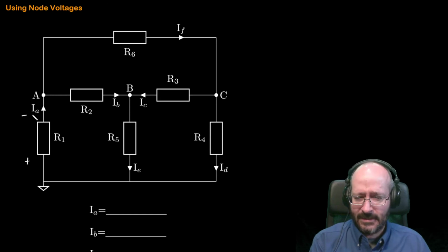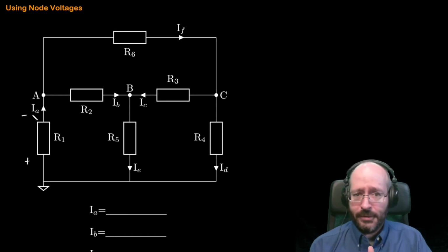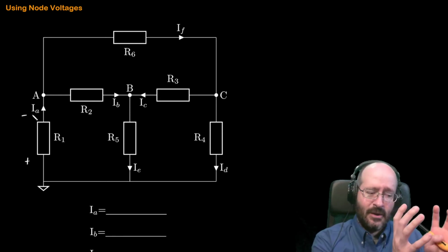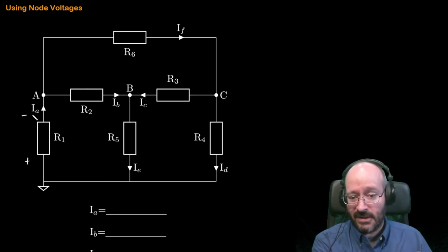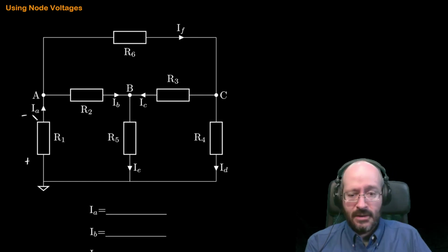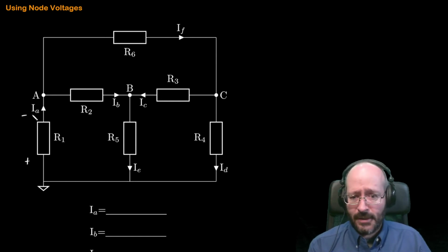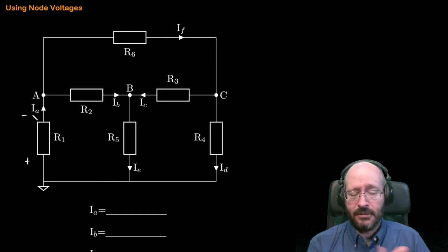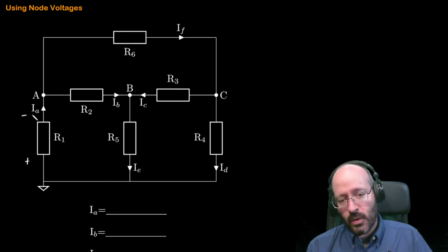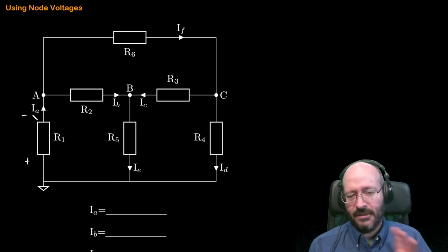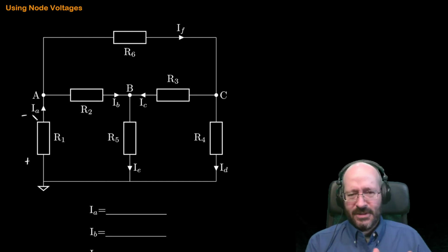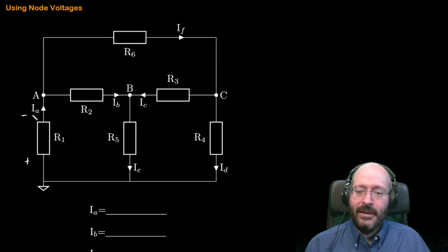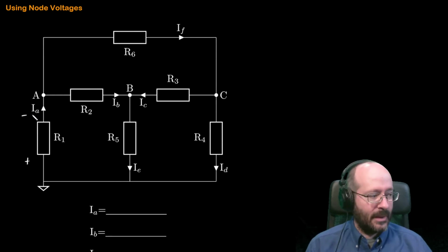flowing through the resistance. And we're going to use that voltage because we've got to relate our non-reference node voltages, even our reference node voltage, honestly, to the current. And we're going to do that with Ohm's law, similar to how we did it with mesh analysis, just backwards. And you're going to find that's the case with nodal analysis versus mesh analysis a lot. There's a lot of overlap, but we're just kind of swapping things around. But the approach is generally the same.